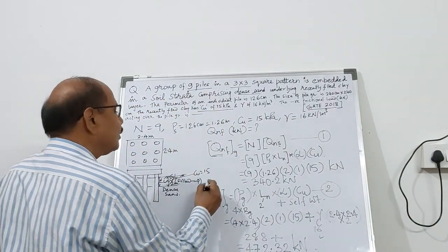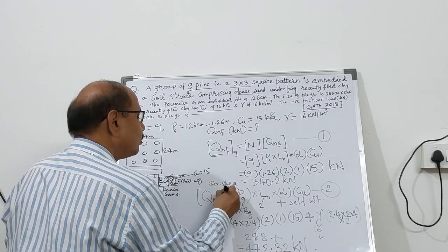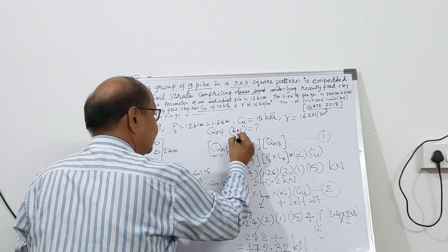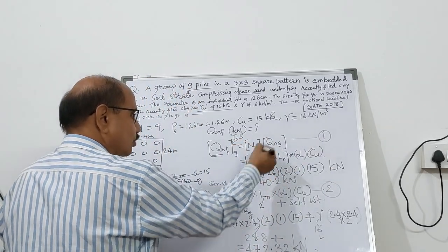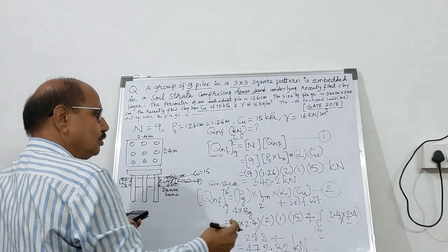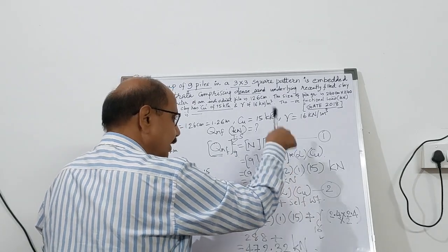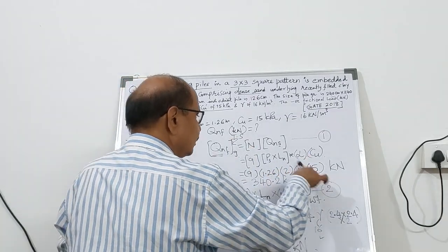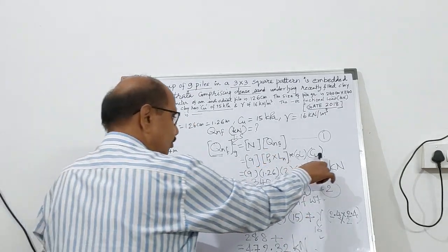So based on group shear, this formula you should use. That is equation 2. Based on individual shear, you should use formula number 1, where the number of piles, 9, you have taken, and you have found out the negative skin friction a single pile can carry. So the perimeter of the single pile into the compressible zone, that is Ln, and then you should multiply it by the frictional or the drag force, that is alpha times Cu.